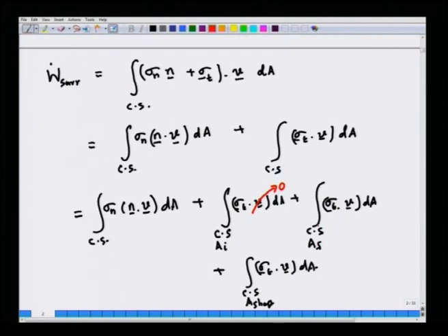If you look at the control surfaces over the flow areas, let us say this is the flow, and this is the direction of velocity. If you choose the control surface such that the unit normal is perpendicular to the flow direction, then the tangential stresses will act in the direction perpendicular to the velocity. So, these 2 vectors are orthogonal, and this can be set to 0. If V is perpendicular to the control surface, that is if n is parallel to V, that means the velocity vector and the shear stress vector are orthogonal to each other.